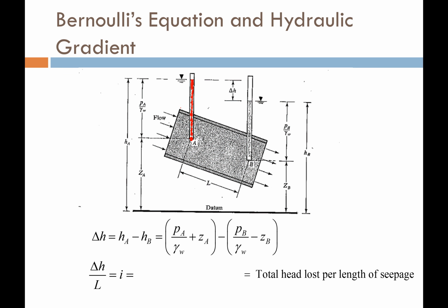How can we relate that level of energy in that water to total head? If I draw some line, any line, and I call that my datum. The definition of a datum is a reference line, but it's constant. It cannot move. You can't shift it. Once you define your datum, it is what it is.